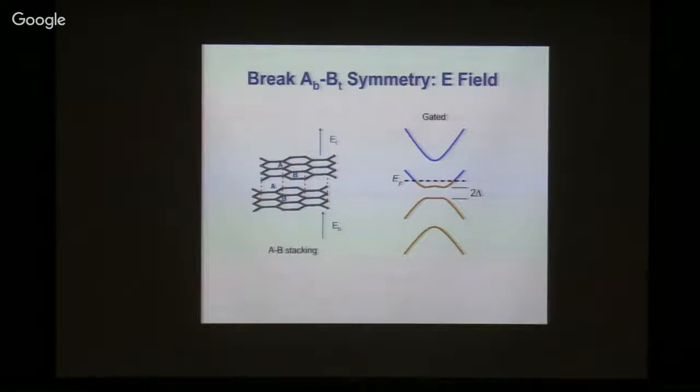If you apply an electric field in a piece of graphene, like in a typical field effect transistor, it turns out you can also control its carrier concentration. So in bilayer graphene, we actually have a quite unique system where you can have a continuously tunable semiconductor band gap as well as tunable carrier concentration simply by applying an electric field. And the band gap and the carrier concentration are the 2 most important parameters that describe a semiconductor. Of course, you would like to control this carrier doping and band gap independently. And that can be achieved in bilayer graphene in a fairly straightforward fashion.